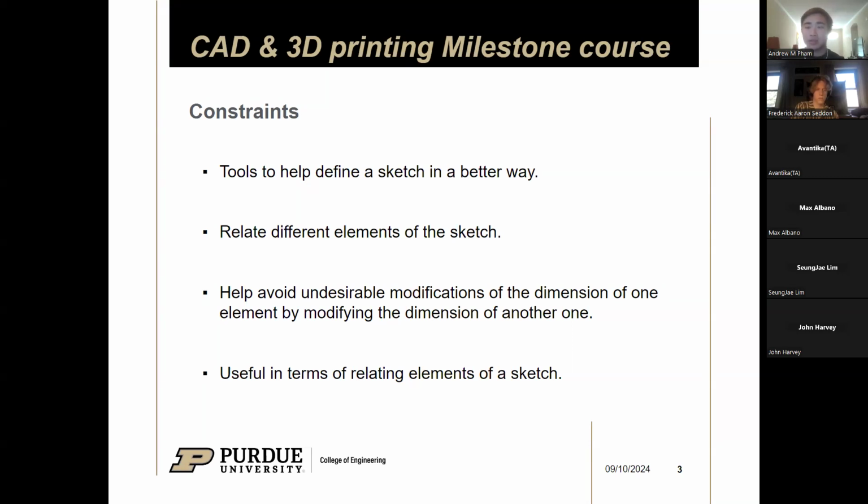The reason why we use geometric constraints is that it can really simplify our sketches visually. If we want something to be shaped in a general way, but we want maybe, let's say, 1 or 2 adjustment points, we can use geometric constraints to lock certain elements down, and then just focus on what we really want to be adjustable.